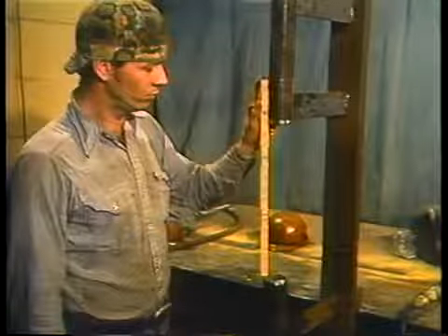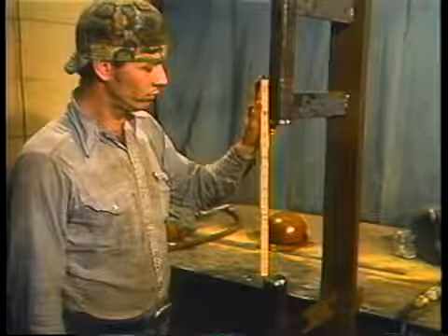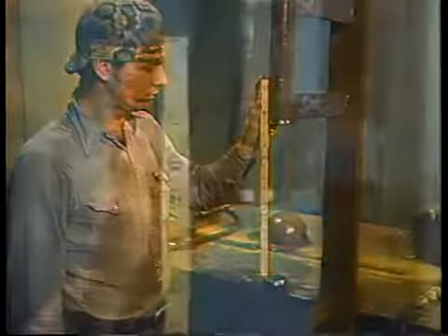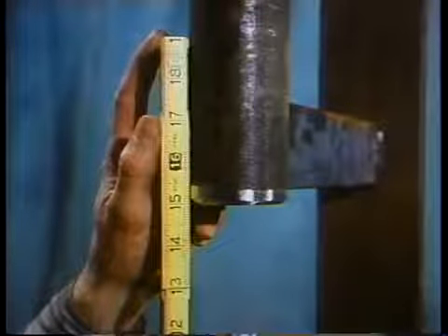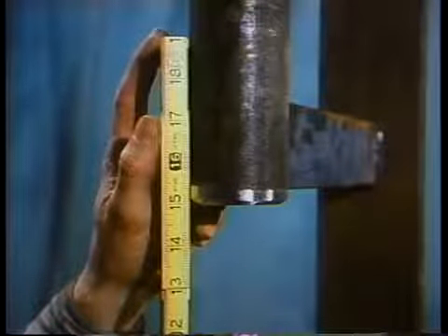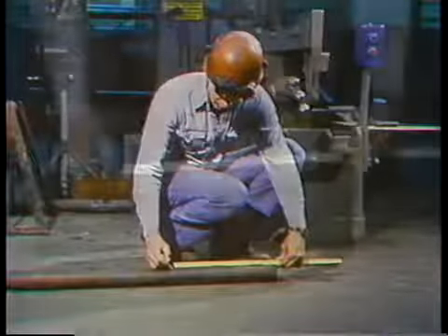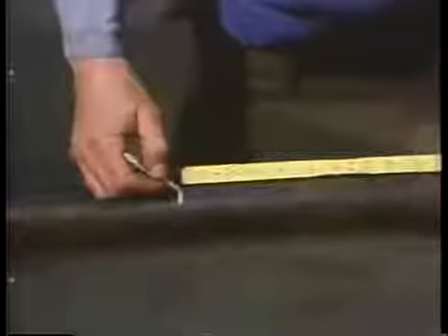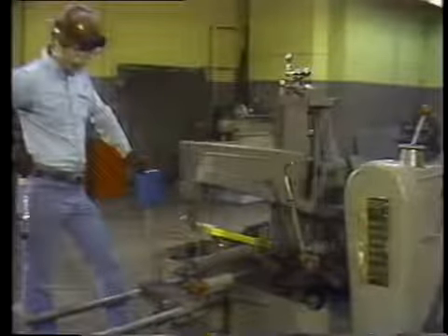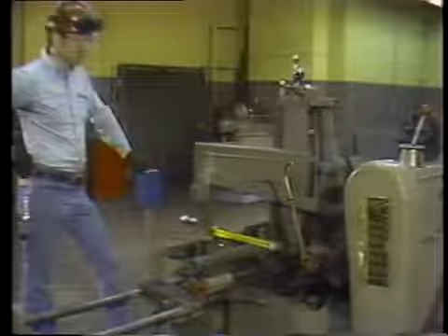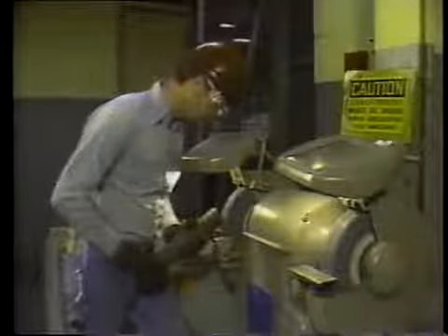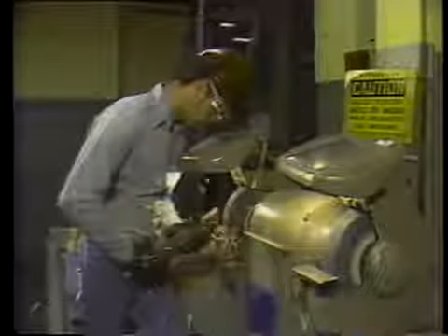Next, the distance between the free ends of the tube is carefully measured. It's important to get an accurate measurement so the replacement section can be cut to fit in the available space. Space is left for the beveling that is done to the free ends of the tube and to the replacement section. The replacement piece may be cut on a saw in the shop. The ends of the replacement section must also be beveled. This can be done in the shop before the replacement section is taken to the boiler.